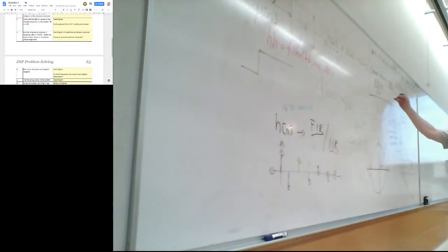The group delay in MATLAB would be filter the phase shift with [1, -1], 1, and then phase shift divided by delta F. Yes, delta F, which is Fs divided by number of points.